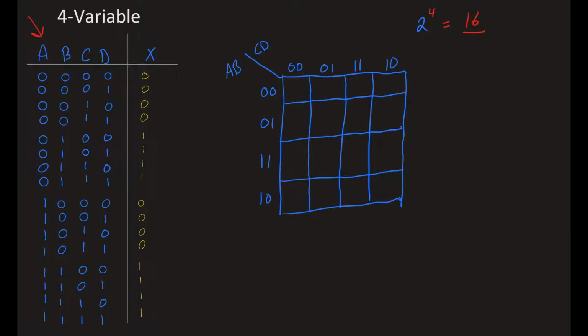And again, our same rules apply. If you go from this box, I'm not going to do them all because I don't want to take your time. But if I go from 0 1 1 0, notice over to here to 0 1 0 0, still only 1 bit flips. If I go from here, 0 0 1 0, only 1 bit flips. If I go down here, 1 0 1 0, only 1 bit flips. So again, that's why this is drawn with that funny numbering system.